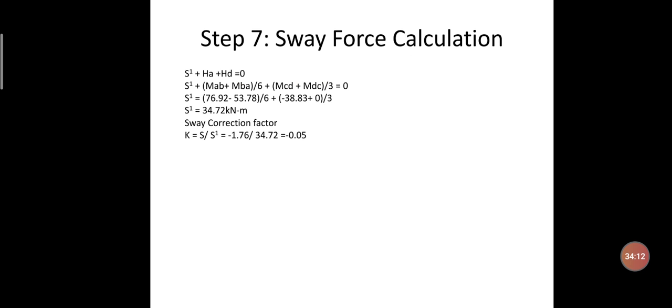So the next is the sway force calculation. For the sway force calculation, I have the sway force as S dash. S dash is nothing but the summation of the reaction which gives the arbitrary displacing force. So S dash plus HA plus HD is equal to 0. S dash is nothing but the arbitrary displacing force.